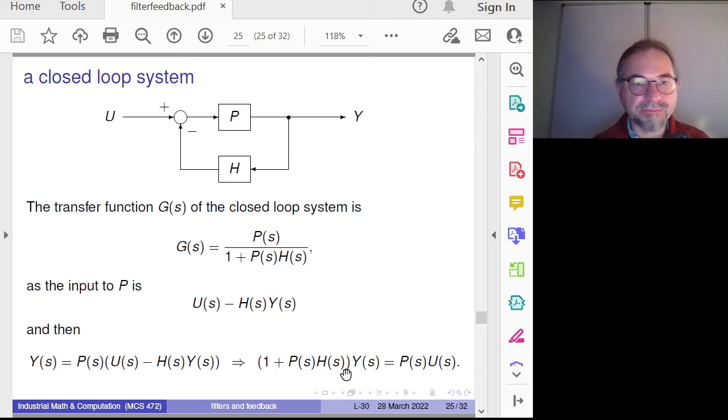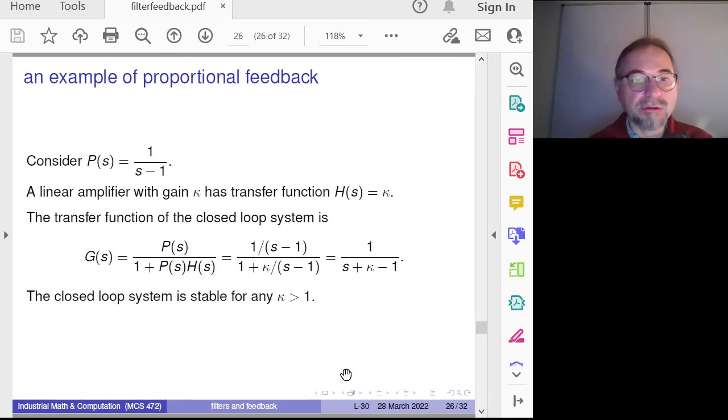So we have the transfer function of the closed loop system, and that's what we're looking at to stabilize a plant. Because what we want is that all the roots of the denominator are negative. So we then have a decaying exponential instead of a growing exponential. Here I will explain this in a minute on the credit card balance.